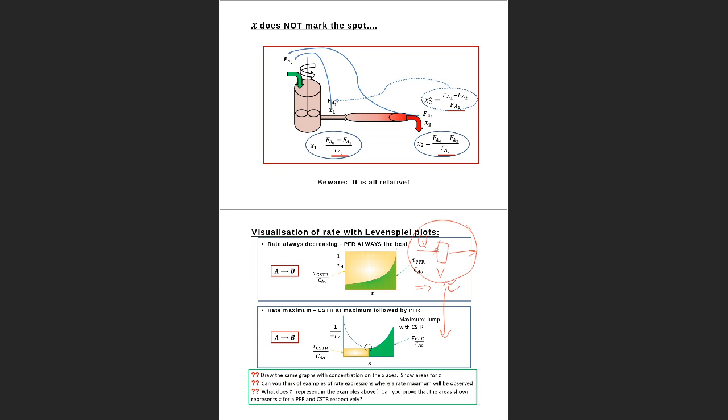Somebody wants to repeat this reaction on a bench scale or a pilot scale. So at least he's got a scalable factor that says, okay, if I now want to change this volumetric flow rate to something bigger, in a bigger reactor, how much bigger must it be? The residence time gives you a good scalable factor to translate between different size bases. It also gives you a reasonable starting point, so you can go into the literature and say, typically, these kinds of reactions require a residence time of that. So it gives you a starting point for your design.